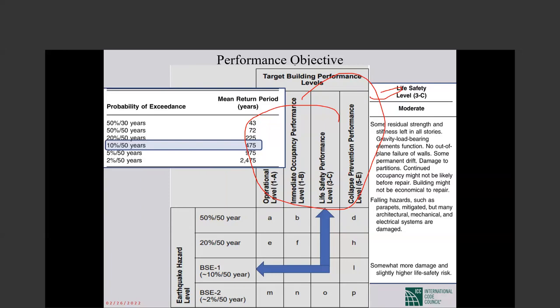So we have demand, we have capacity. And the calculation of capacity is according to whatever we learned till now. It's nothing new. But the limits for each performance level are new here. Very nice. And most of our attention will be on the calculation of demands for the different levels of earthquakes. One of them, for example, let's say performance level life safety.